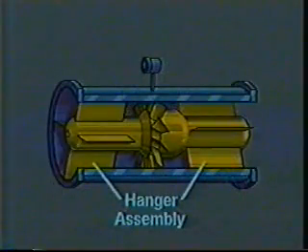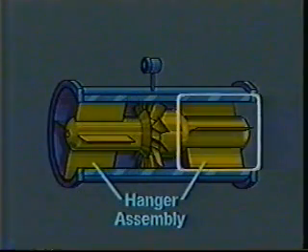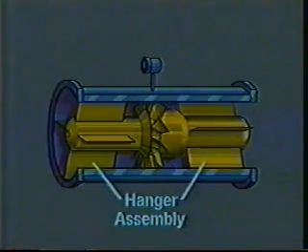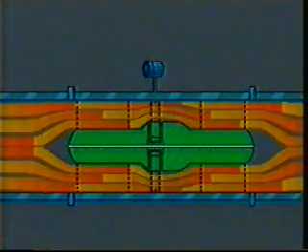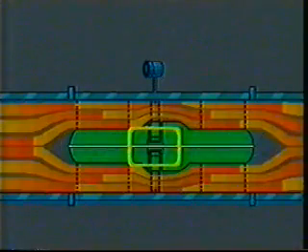The turbine rotor is mounted on a shaft by an up and downstream hanger assembly. Although these hangers might resemble straightening vanes, they do not perform this function. The turbine rotor blades are set at a predetermined angle. This angle relates the flowing stream, angular velocity of the rotor, and the frequency of the meter. The rotor rotates on the center line shaft by means of a bearing. This bearing is either lubricated by the meter fluid itself or permanently sealed. However, to minimize the load on the bearing, the rotor also floats.